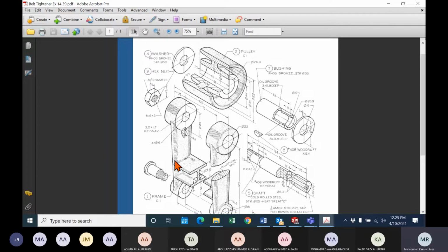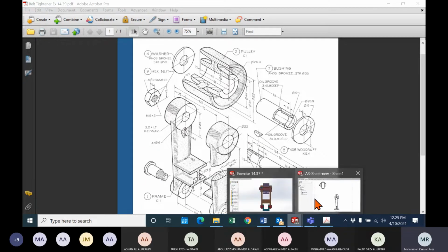The fasteners, meaning nuts, bolts, screws like this one. And keys also. And the shaft, if it is solid. Our shaft is not solid, it is hollow, the hole is inside, so the shaft we will section. But for example this nut, this screw, and this key, because key is also a fastener, these we do not want to section. So we don't want to section these three parts. So now we can select here during this step.